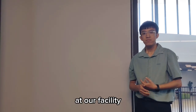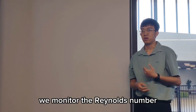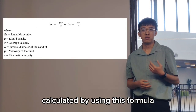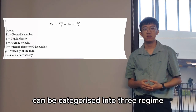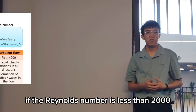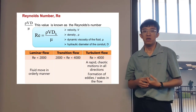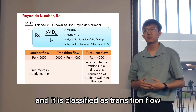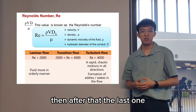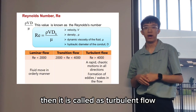In our scenario, cumene is treated as an incompressible fluid. We monitor the Reynolds number calculated by using this formula. The liquid flow through the pipeline can be categorized into three regions. If the Reynolds number is less than 2,000, then it is classified as laminar flow. If the Reynolds number is between 2,000 and 4,000, then it is classified as transition flow. Then the last one, if the Reynolds number is more than 4,000, then it is called turbulent flow.